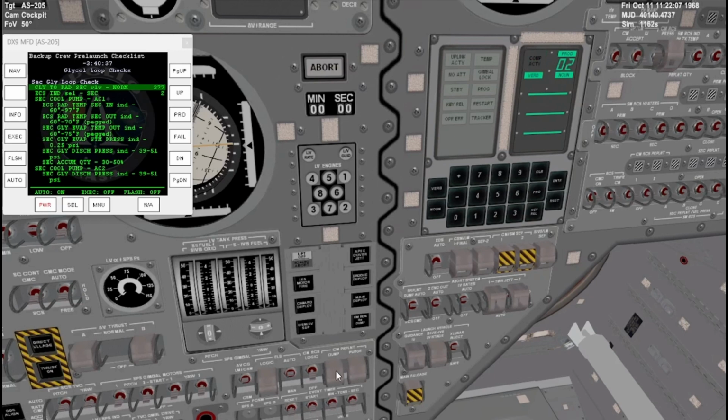Dump will open all command module RCS valves, and the purge will instantly boil off the helium. The loss of helium will cause a significant pressure change in the fuel, leading to instant evaporation of the fuel, and they will flow out of the RCS ports. The launch escape motor fire, canard deploy, CSM LV SEP, command module RCS helium dump, the main deploy, the drogue deploy, and the apex cover jettison are all irreversible. In addition, anything under the sequencer that is guarded is an irreversible action.